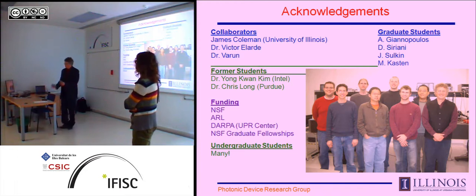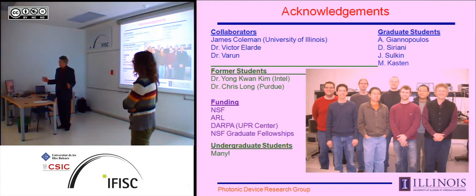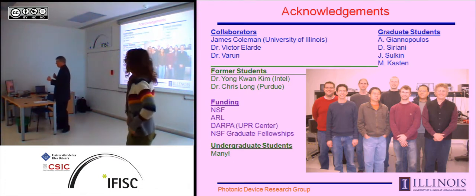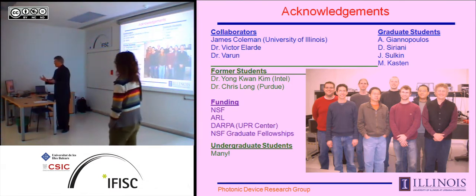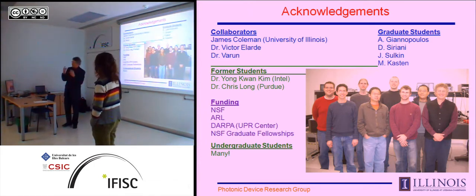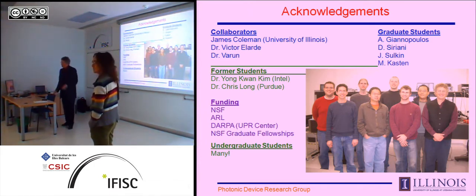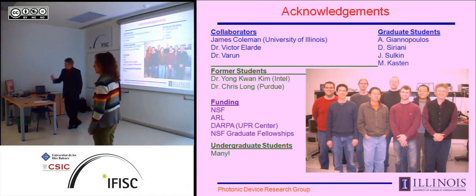So again, we're maybe not exactly at this condition of constant photon density. Although, what I should say is, if we inject the same carriers into one and extract them out of the other, then we can keep a constant bias current. To that extent, it's independent of the total photon density. The total photon density should remain the same; we just displace the charge locally. Through that we change the index, through that the cavity, and through that the boundary conditions of Maxwell's equations, which change the output.